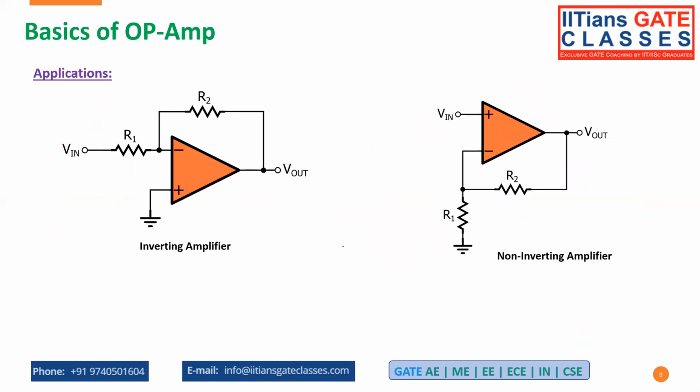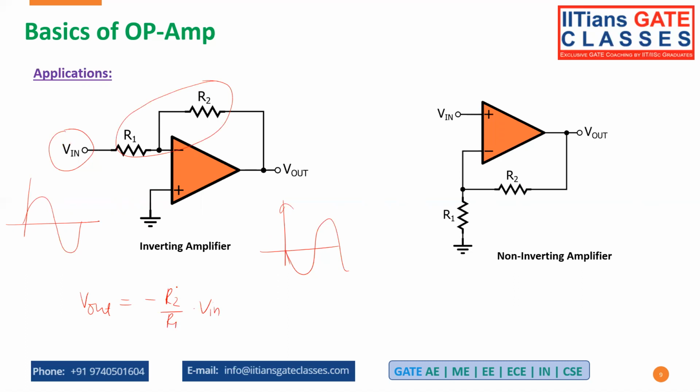The basic applications that we are using, the first is the inverting amplifier. As I told, in the inverting amplifier you are applying the input signal to the inverting terminal of the op-amp. If your input is like this, you will get the output as inverted. I'm not considering the amplification part, but amplification depends on the ratio R2 upon R1. So basically the output is V output equal to minus R2 upon R1 into V input. Based on the ratio R2 upon R1, you are going to increase the strength of your signal by that amount. This is the basic aim of the op-amp circuit that we are using.